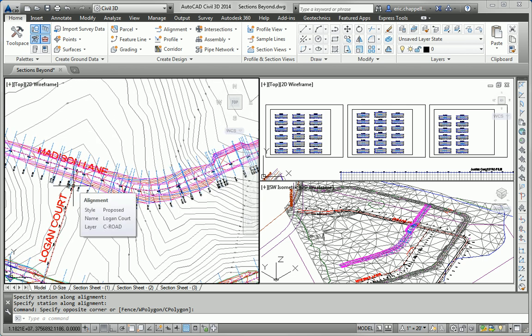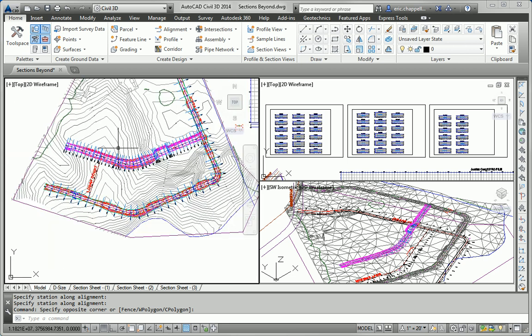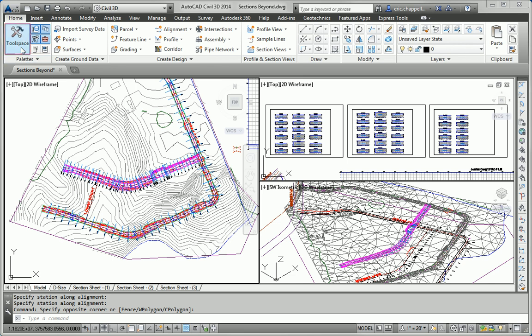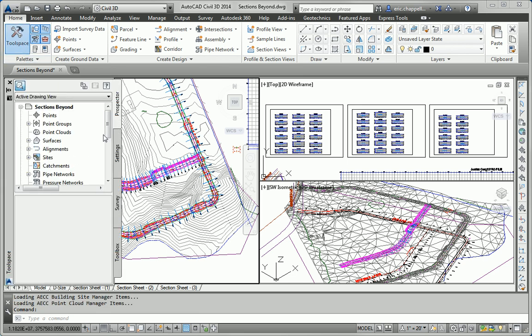Step 3 is to create a sample line group intended for sheet creation. And instead of going along the corridor sections now, we want to go along 50-foot increments, even increments. So the first thing I'll do, and it doesn't tell you to do this in the exercise, I want to hide the visibility of these sample lines. I don't want to erase them.